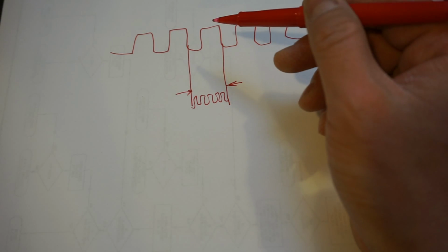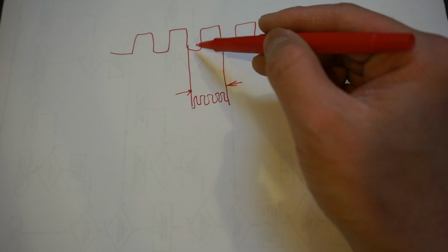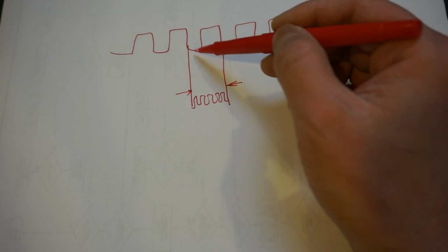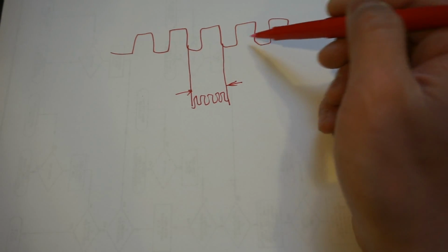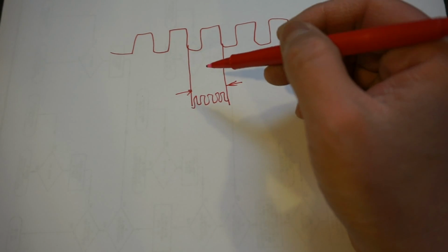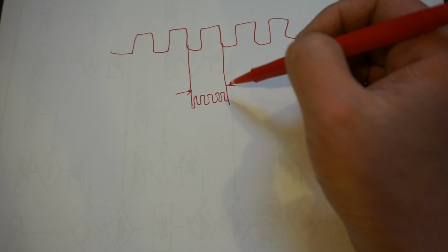Now, there are obviously quite a few advantages to this method. For example, if I wanted to make it more accurate, I can include more input pulses instead of just 1. I can count 10 pulses and use that interval to average out the uncertainties of my clock counting here.